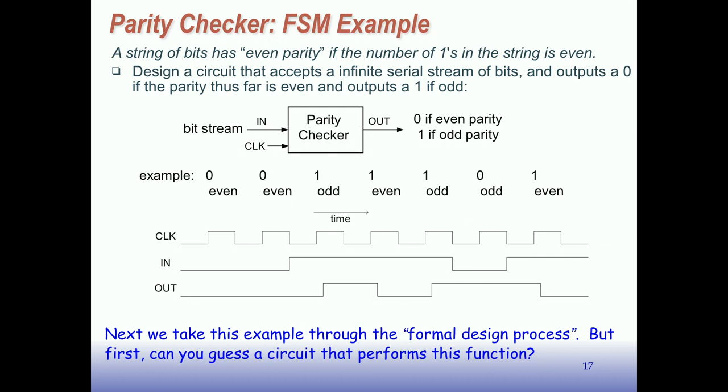And that's the output. This is D, that's the Q. Or you could just have it sum, and since it's a 1-bit number, it'll just overflow and be 0 if it's already. Oh, do sum, yeah. Well, a sum, if you look at how to sum adding bits together, it's just XORing them. So it's the same thing. Like I said, this is addition mod 2. So yeah, it's a really good guess.